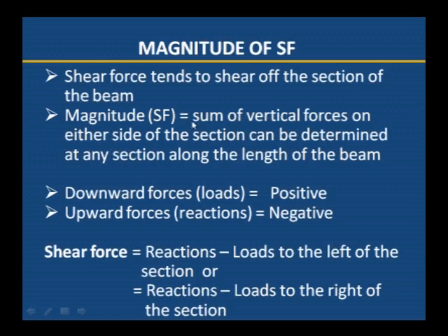Then how to find the magnitude of shear force? The sum of the vertical forces on either side of the section can be determined at any section along the length of the beam. We have to find the sum of the vertical forces on the left or right of the section of the beam.